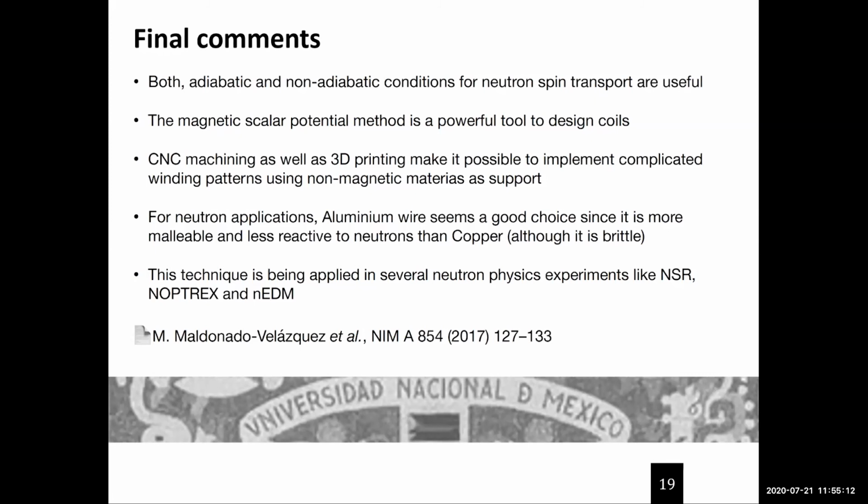And finally, I think the end caps were causing some trouble because we didn't think of a way to mechanically attach them. So it turned out to be very sensitive to the proper alignment of the end caps. So that's another lesson we learned, having a way to align and mechanically mount the end cap to the rest of the coil.